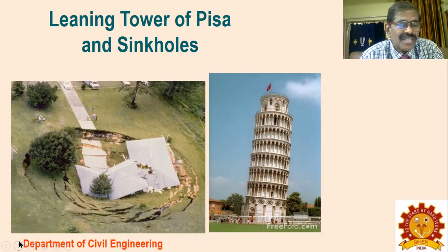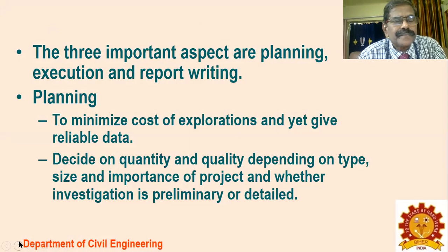You can see that sinkhole here where a tree is already gone, and one structure is slowly going under the ground level. That's how the sinkhole develops if the condition of the soil is not properly investigated and an aquifer zone is fully waterlogged. Then such things can happen to a real structure. So soil exploration is a must for you to understand how to erect the structure.